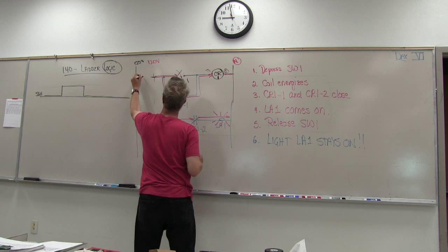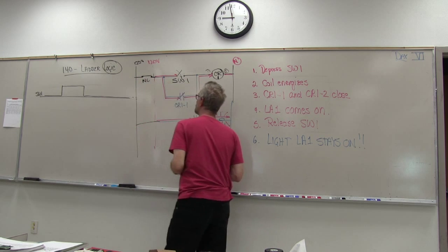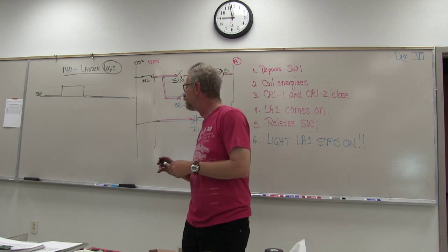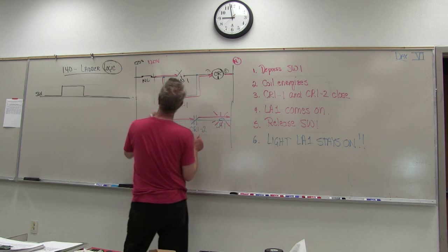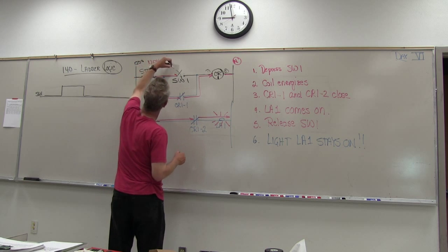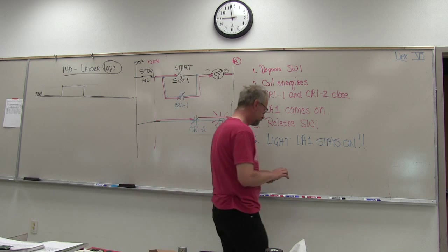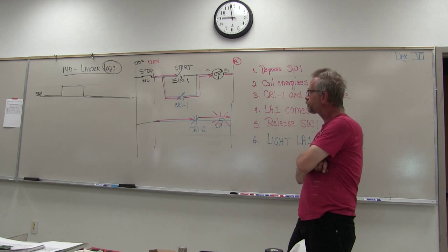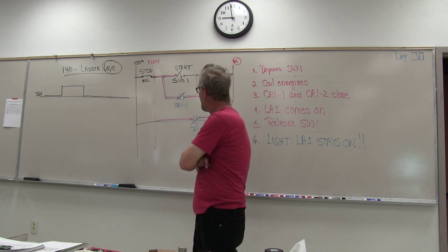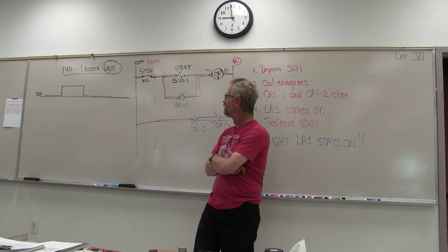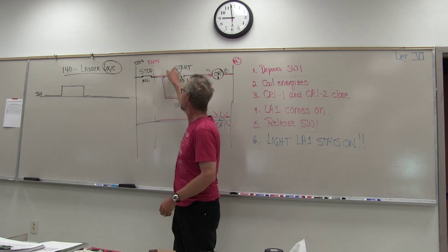And put a normally closed switch in there. And we would label that stop, and we would label that start. Now, what you'll see is we'll talk about that later on. Actually, you guys will see this in the lab, that this then becomes what we call a dominant stop circuit, because the stop is before the start.